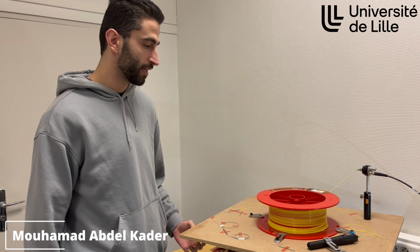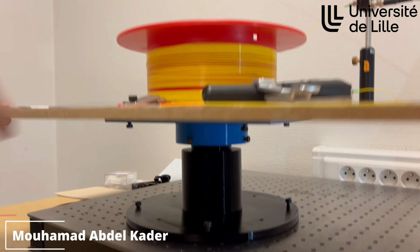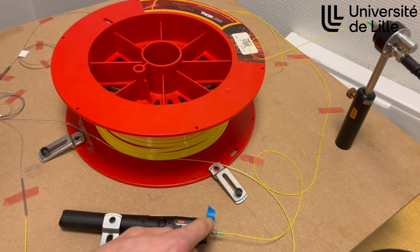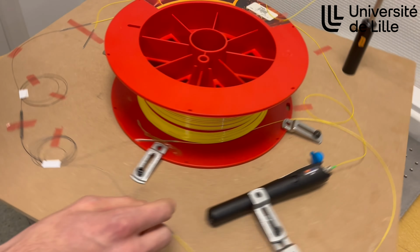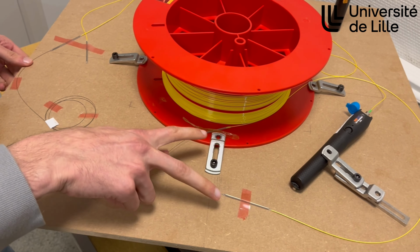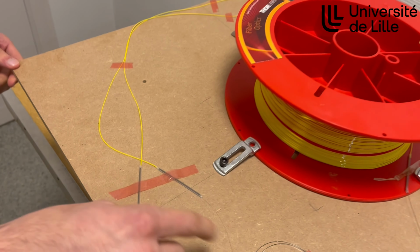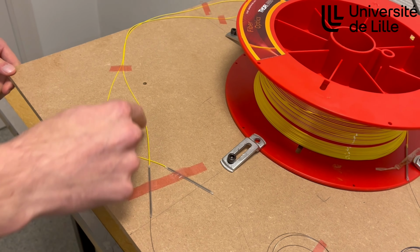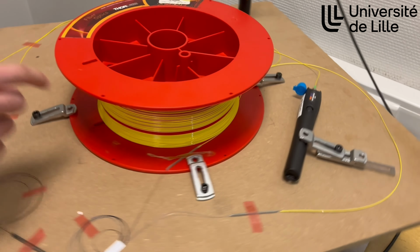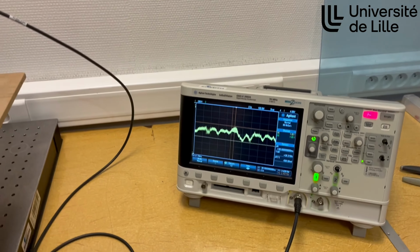So now I will speak about the experimental setup. Here we have the 3D printed rotational base. And here I will show the components. Here we have the laser connected to the optical fiber, and then we have here the coupler, which is spliced with the optical fiber loop. And here we have also the second side of the coupler. The first one is connected to the photodiode here, and the second one is connected to the laser here. And also the photodiode is connected to the oscilloscope.